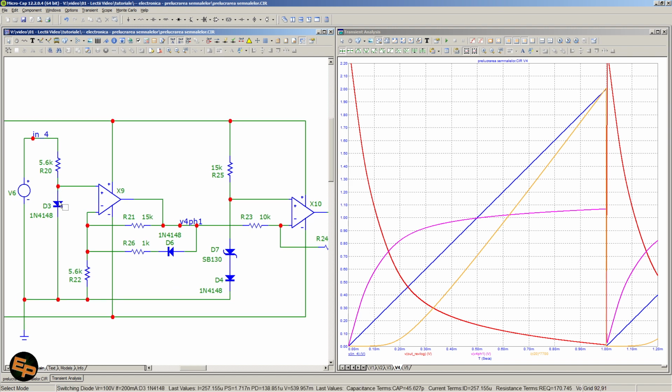Now, after we have done this, we basically have a voltage across the diode that varies sort of logarithmically. We take this voltage, which is very small. It varies between 0 and some 0.7-ish, give or take, and we need to amplify it.